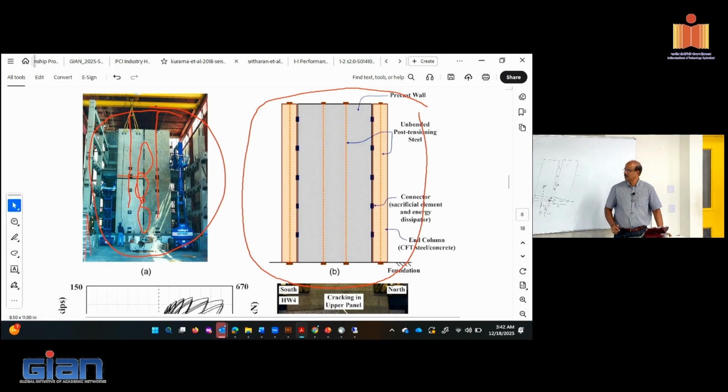So the best choice would be to keep the wall as wide as possible and put some end columns. By having end columns, you can transfer a lot of the gravity load through the end columns if you wanted to. You don't have to engage the wall. The wall can provide seismic resistance and shift the connecting elements to those end regions, and your efficiency comes back again. So we studied this PreWEC system quite a bit as well.